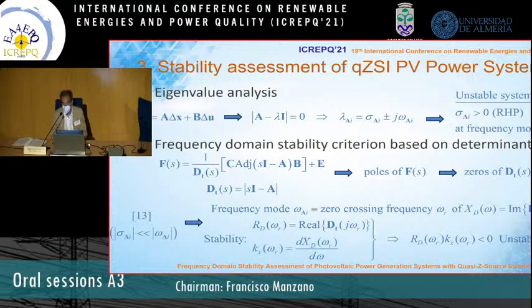With respect to the frequency domain stability criterion, I am going to present this stability criterion based on the determinant of the state space matrix. From the transfer function of the system, we know that it depends on the determinant of the state space matrix, and to study the stability by means of this transfer function, we must analyze the poles of this transfer function. That means the zeros of the determinant of the state space equations.